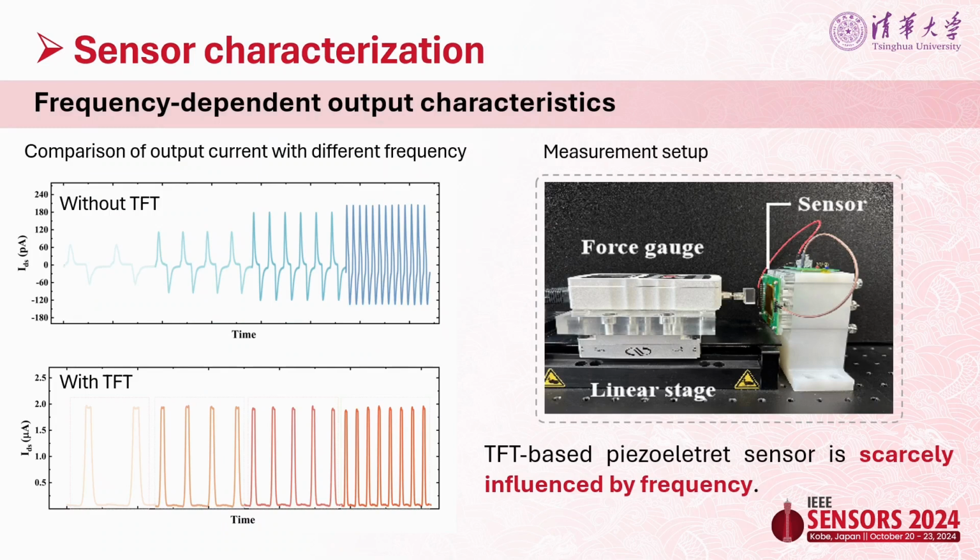The sensing performance of the TFT-based piezoelectric sensors is tested. We first explored its frequency-dependent output characteristics. We compare the output current of the sensors with and without TFT under the force with different frequency. Compared to the sensor without TFT, the piezoelectric sensor with TFT is scarcely influenced by frequency. This undoubtedly enhances the sensing accuracy.